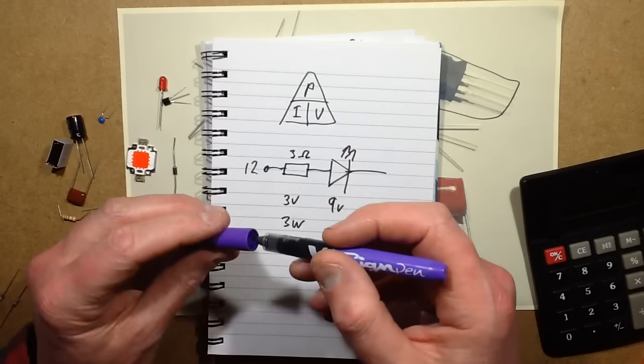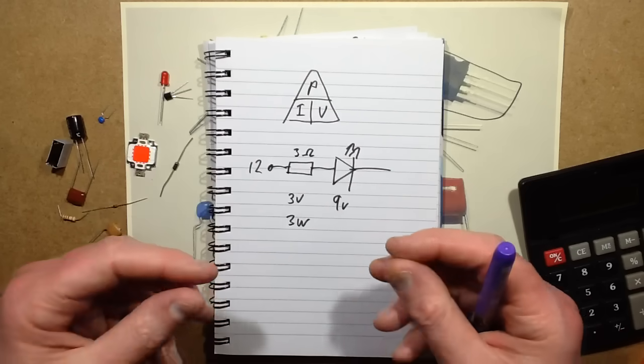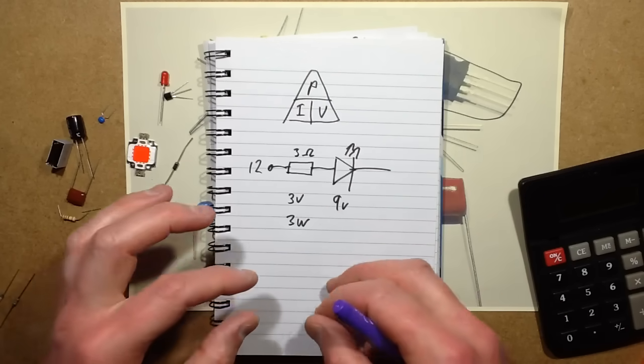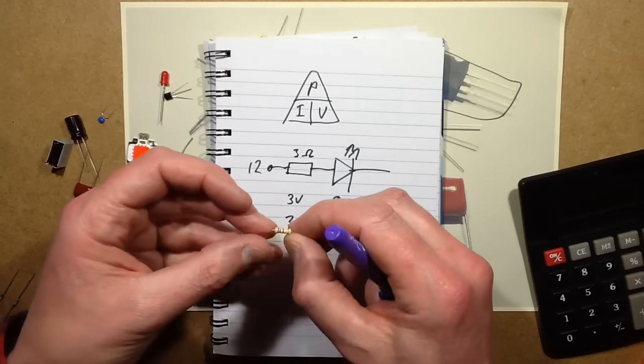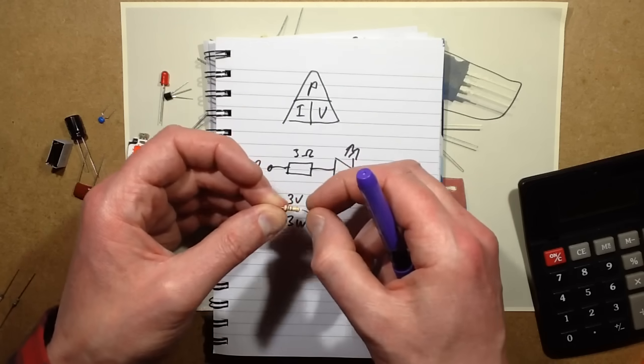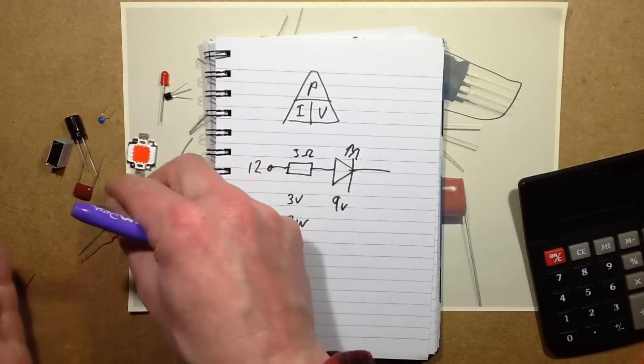You often see resistors that have just been pushed too far on printed circuit boards. You know, they've been designed and they've said, I need a 1 watt resistor. They use a 1 watt resistor, and instead of a nice colour code, it's basically the whole thing is just brown, and the circuit board shows heat around it as well. So it's good to dissipate, get rid of that heat.